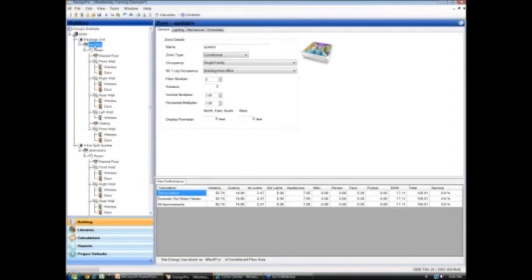It defines this now as a multi-story house. And so for natural ventilation, there's assumed to be more height difference between the windows when you open windows at night to let in your night breeze. 2-story homes have more distance between the windows, and so we get more natural ventilation between them than we do in a single-story house.